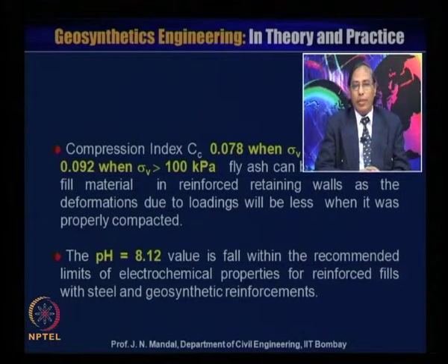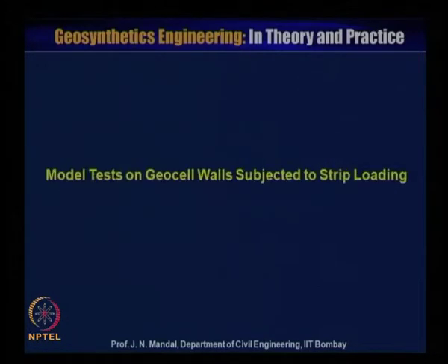The pH value of 8.12 falls within the recommended limit of electrochemical properties for reinforced fill with steel and geosynthetic reinforcement. So, it satisfies all the criteria.